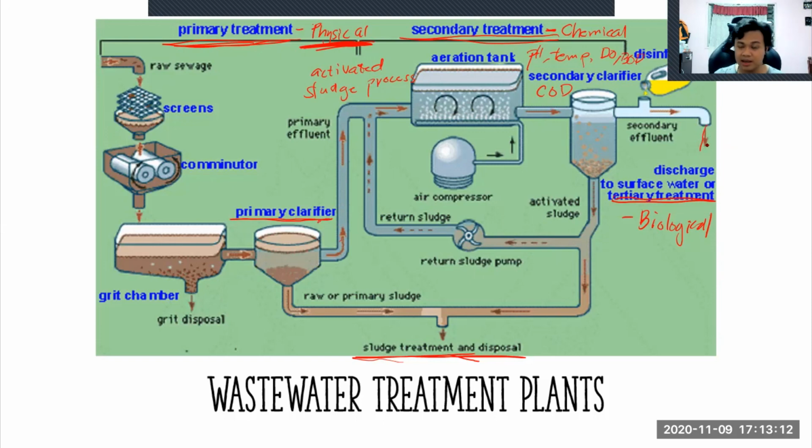What they do is that before they discharge it to any body of water, they let it pass through a fish pond. So you have fishes there, usually koi, in that fish pond. And if those fishes die, meaning the DO, the dissolved oxygen level of your wastewater is bad, so it's really low.